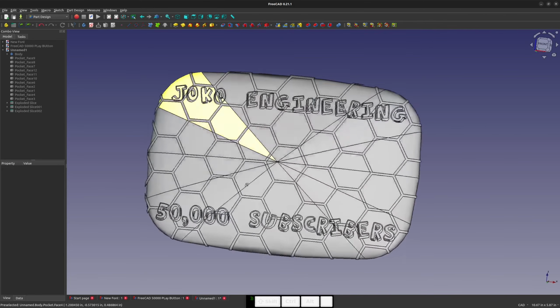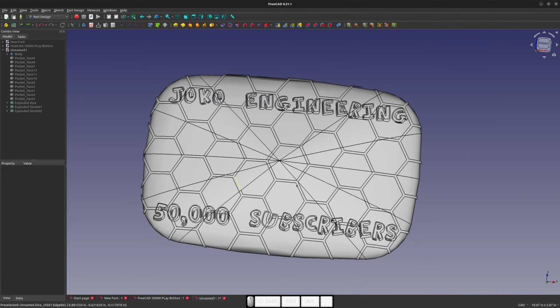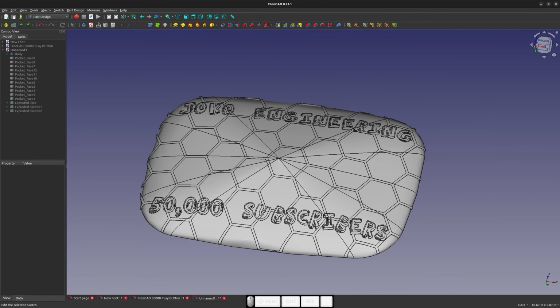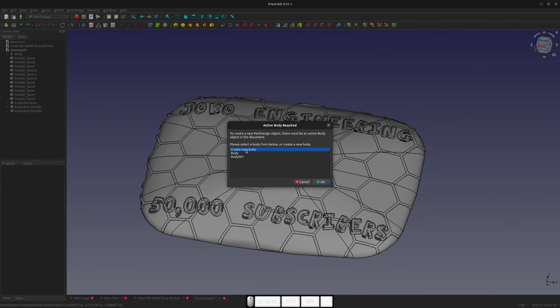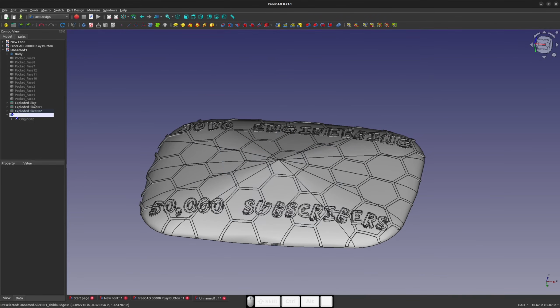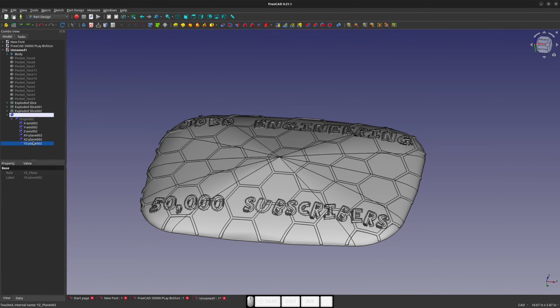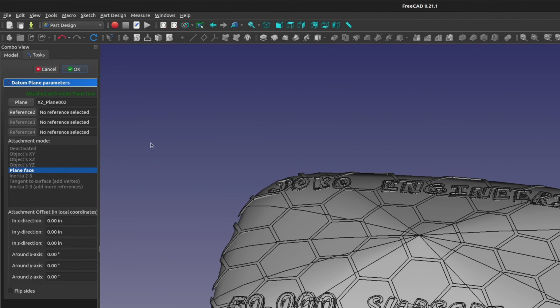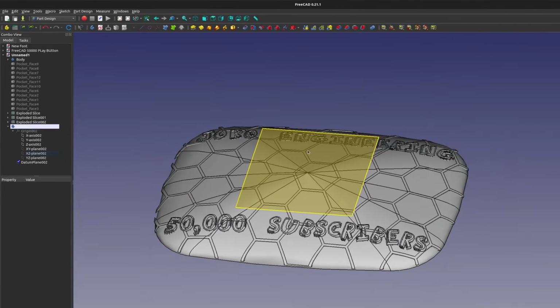All right, so I've got this play button, and we need to add the play symbol in, and then I think we're going to be good, right? I think we're going to be print ready. So let's go with create a new body, and in my new body, you know what? Let's stand on the ZX plane right there. And we'll make an offset in the Z direction. Might have to flip sides. There we go. Right. So there's my datum plane.